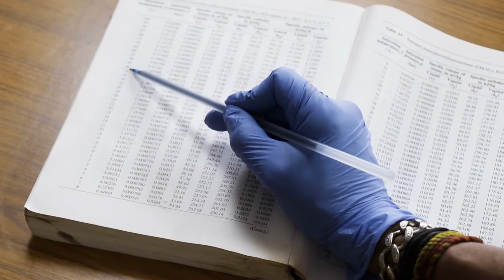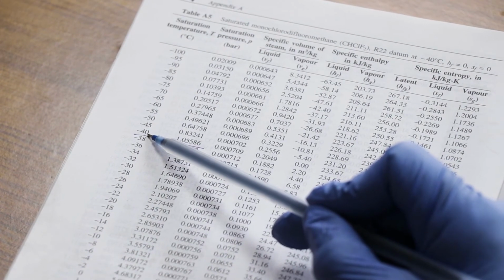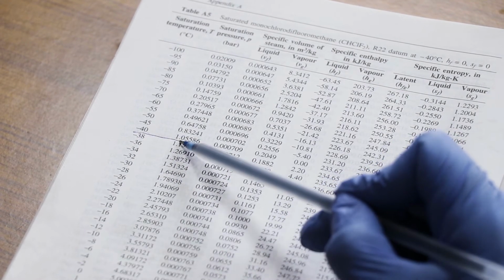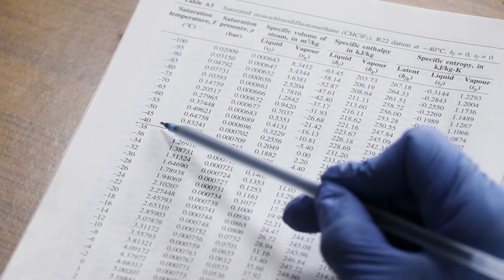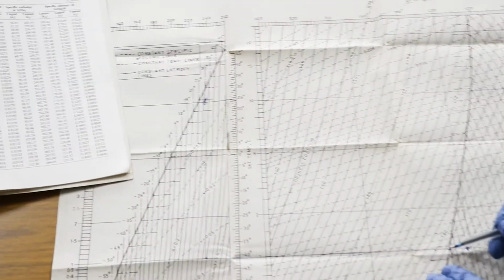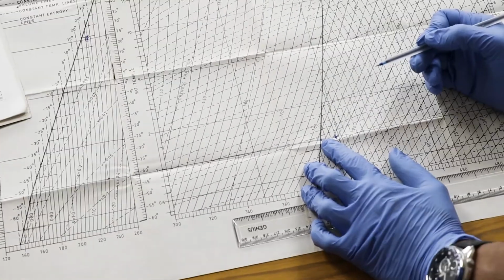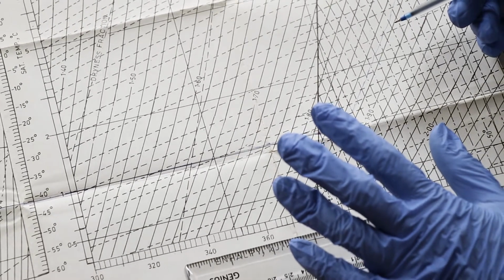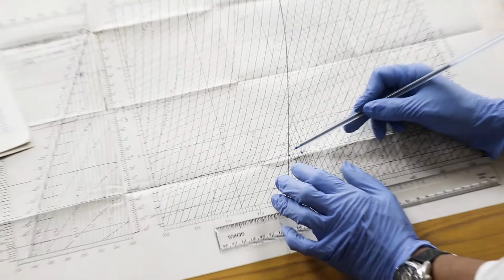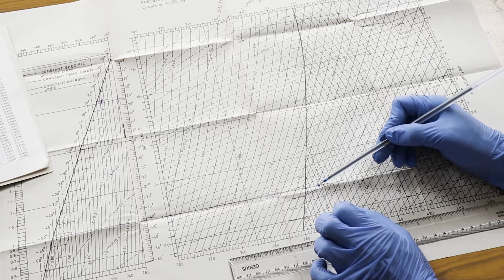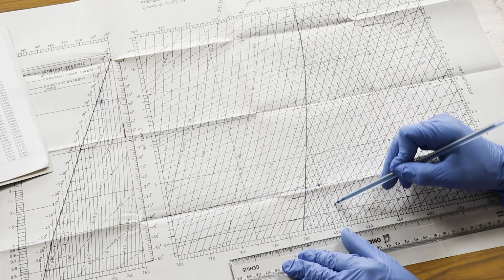The saturation temperature is minus 40 degrees centigrade at 1.05 bar, that is almost 1 bar. The temperature we get from the reading is 26.4, which is more than minus 40 degrees centigrade, so this is not the saturation point. So we are certainly in the superheat zone. We have to see where the 26 degree is. This is the 25 degree line, and 1 degree more from this.